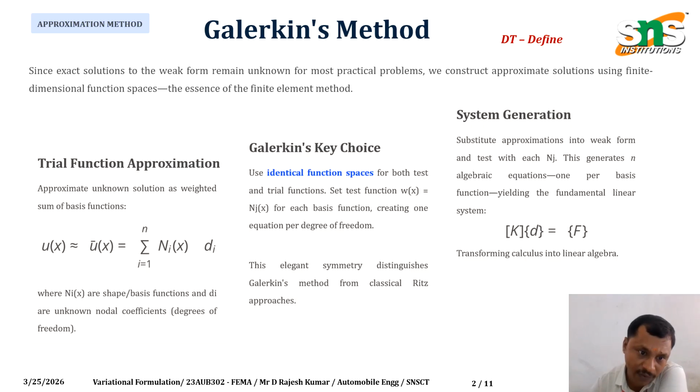We use linear polynomials, quadratic polynomials and cubic polynomials. These are called shape functions in finite element terminology because they define the shape of the solution within each element.